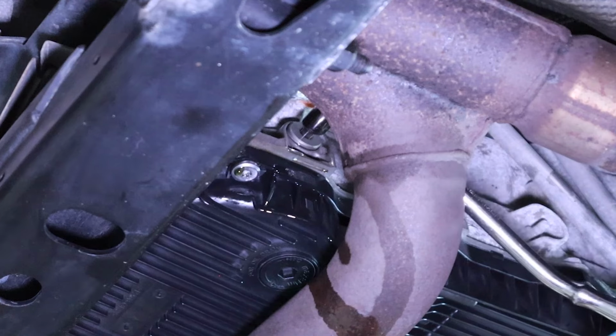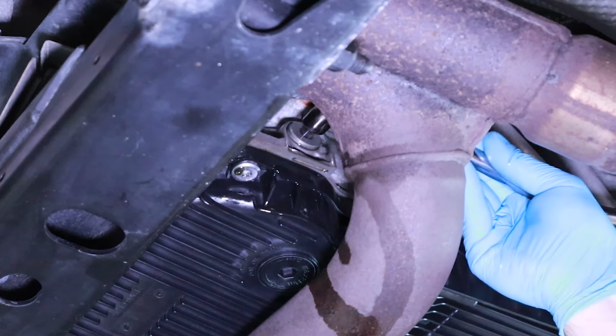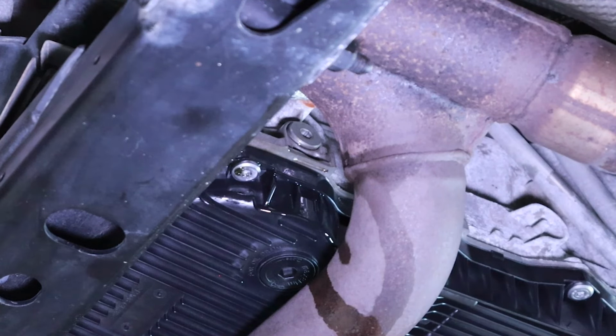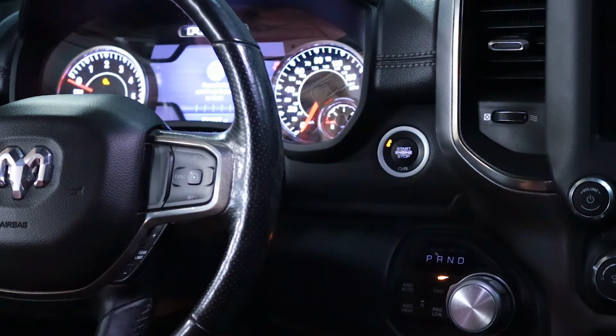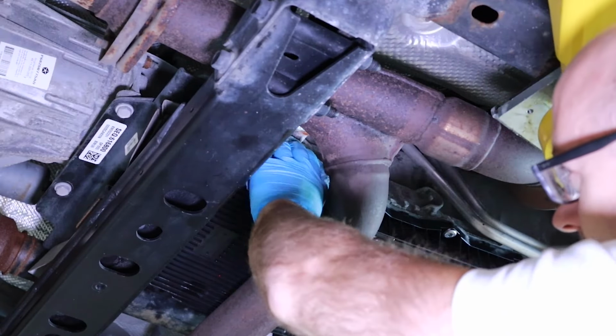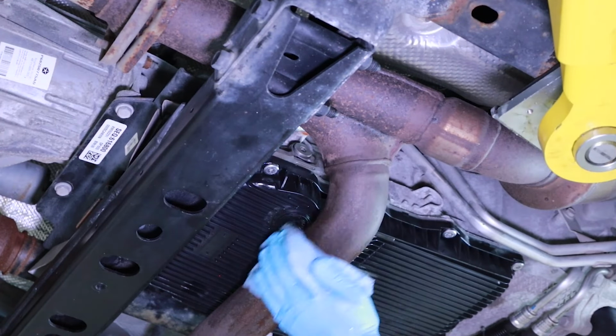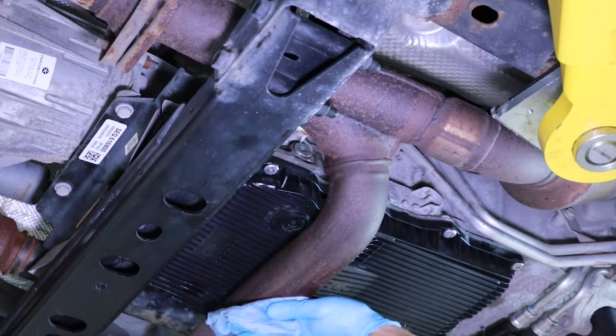If no fluid was flowing out from the fill port when you remove the plug, you will need to pump more fluid into the transmission until you experience a light trickling stream coming out of the fill port between the 86 and 122 degree temperature window. Last, turn off the engine and allow the transmission and exhaust to cool. Once this is confirmed, use a rag to clean any excess fluid from around the transmission pan and fill plug areas to help confirm that you have no leaks.